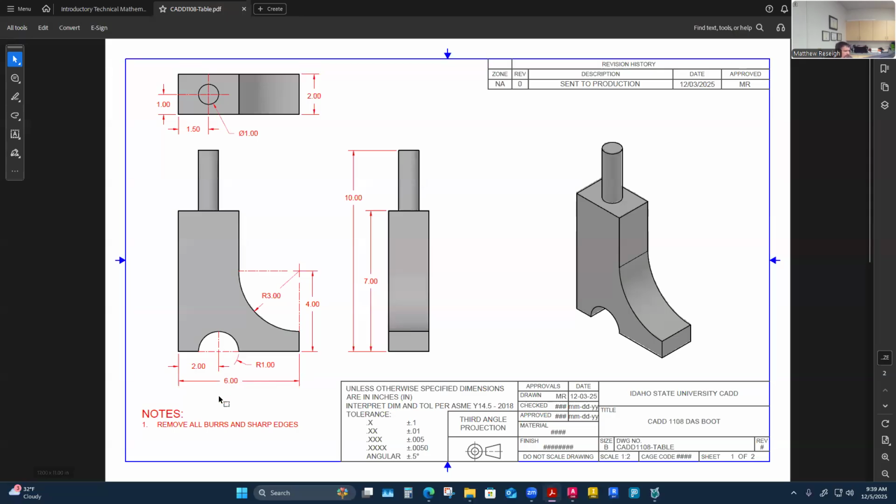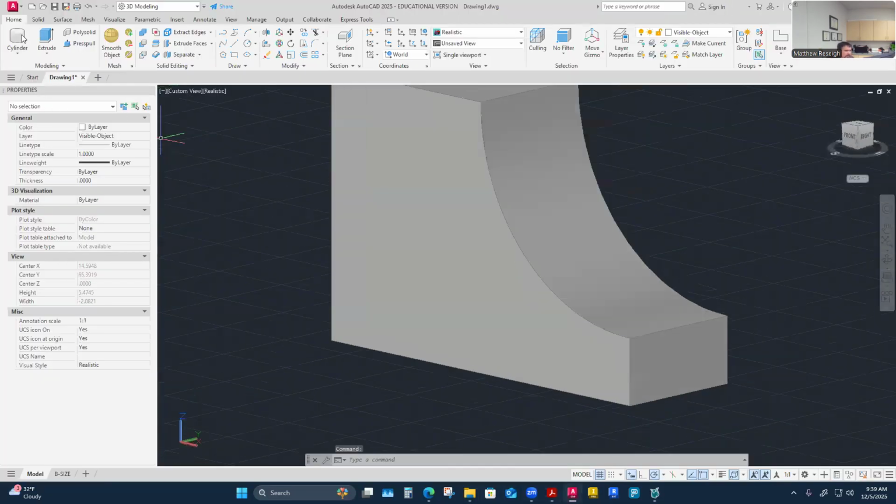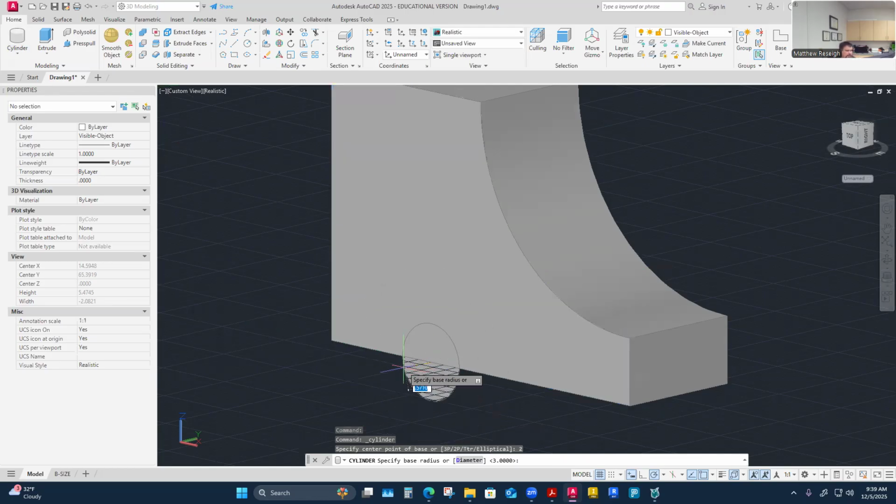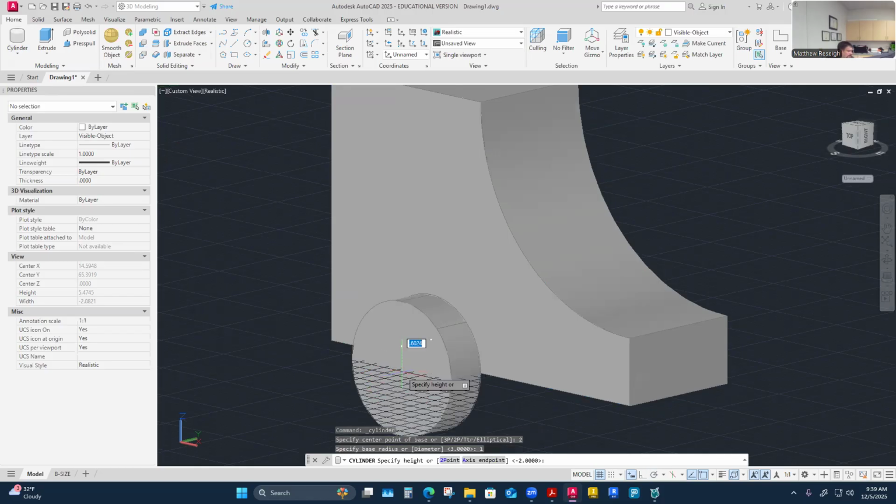So I'm just going to draw the full cylinder and pretty much cut half of it. Let's see here. Yeah, that actually does work like you would cursor over on your 2D drawings. As long as you stay with this plane selected and then that point and then drag along it here and say two, it's going to move you over 2 inches from there, and it'll allow you to put this 1 inch radius cylinder in.